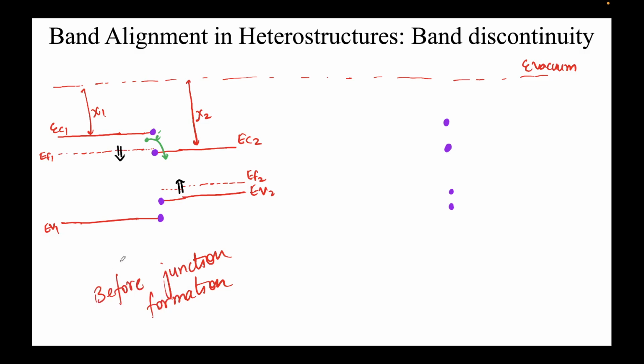Second thing that we must ensure is that the Fermi level will remain flat throughout. So let's say this is the Fermi level, so EF1 will now become EF2 equal to EF, which is this. First we'll do the simpler things. In the bulk, the Fermi level on the left will be the same gap as this, so EC1 will start from somewhere over here like this.